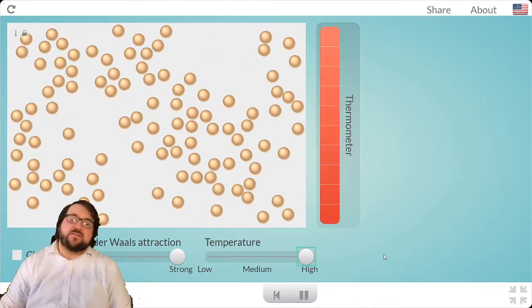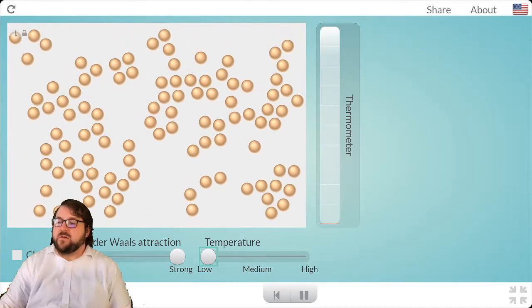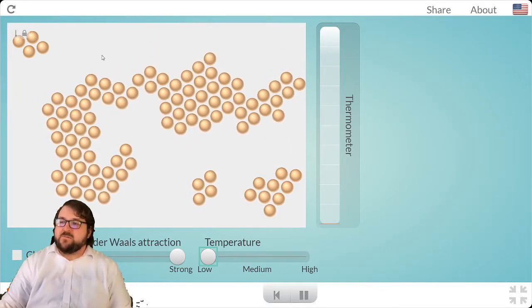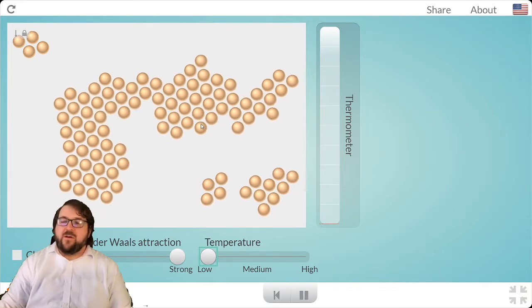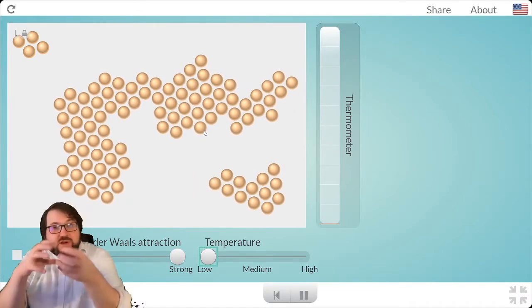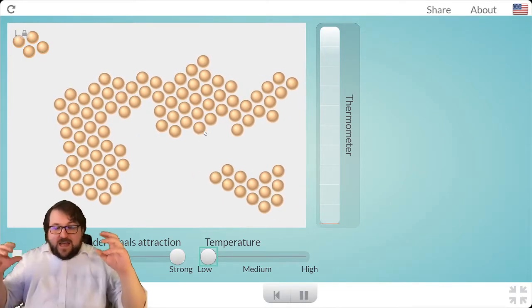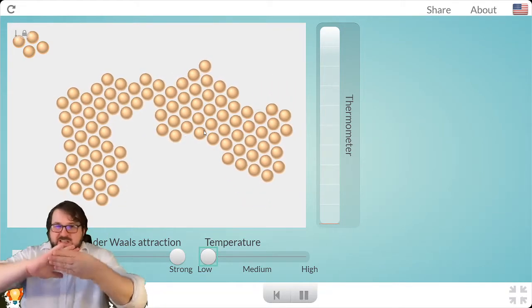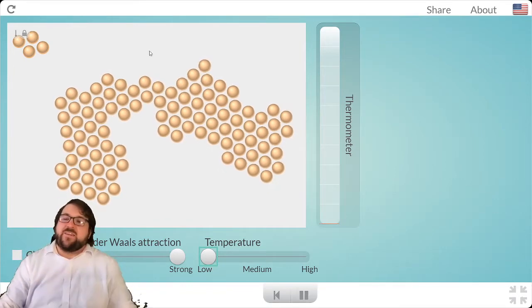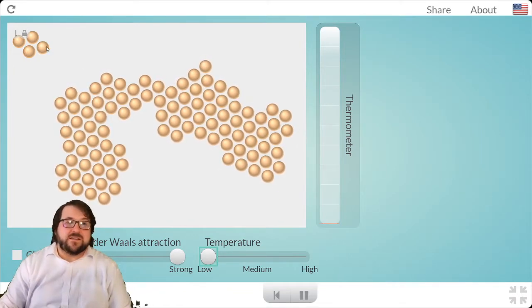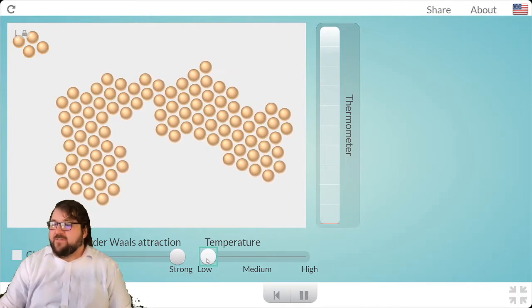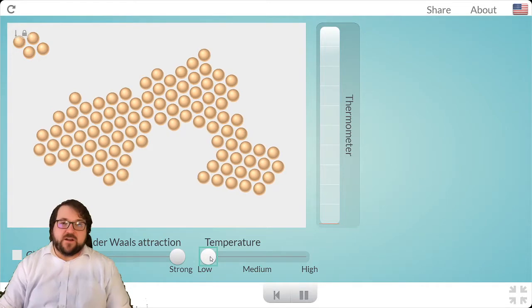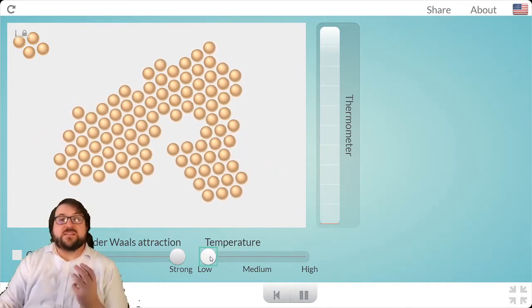And we also saw what happens when you cool it slowly. Now you can see we've got these separate crystallographic domains growing, and then they're all attaching together. This is how that little triplet must have grown. We had them cooling a little bit too fast, and they started attaching to each other, but still growing together. And notice we've got this over here that's doing nothing. So that might eventually become a passenger in there. So when you're growing yourself a crystal, what you want to do is do it as slowly as possible.